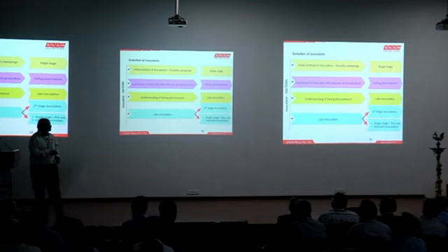So late inoculation. And when late inoculation comes into the picture, how do you add late inoculant? Either you add it manually, or you have an automatic weighing and dispensing system, or you have inoculation done inside the mold, which we call in-mold inoculation technology.